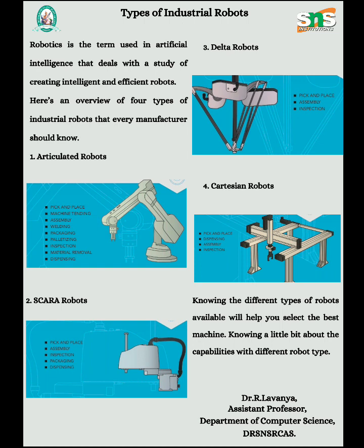It typically consists of 3 or more linear actuators assembled to fit a particular application. Positioned above the workspace, Cartesian robots can be elevated to maximize floor space and accommodate a wide range of workspace sizes. It typically uses standard linear actuators and mounting brackets, minimizing the cost and complexity of any custom Cartesian system. Higher capacity units can also be integrated with other robots as end effectors to increase the system capabilities.